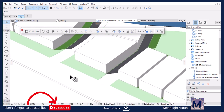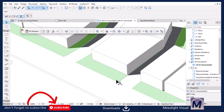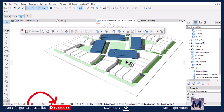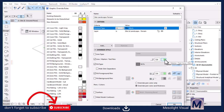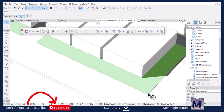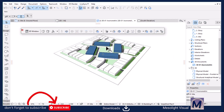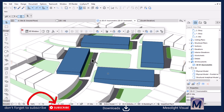So another thing that I can edit is the outline for the landscape. I can make it gray on the same color so that I have the continuity of the graphics. So I'll go back, and then under the site landscape terrain, edit it, and then change the pen to 0.13, the same color. Then hit OK. Yes, now we have a nice gray outline for our landscape. Perfect.